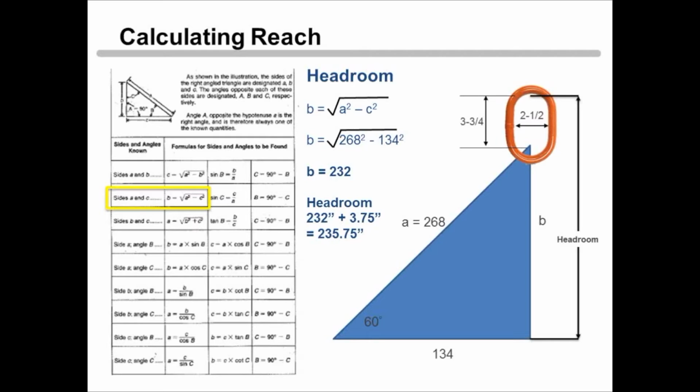So therefore now, is that going to take up too much space? If it's outside, maybe it doesn't matter. So there's two things we need to know. Is the rigging going to work, right? Is that reach going to work? And, okay, great, that achieved my 60-degree angle. And then, of course, how high above the load is that going to work? Because we don't want to find while we're in the air that we're not going to clear something, or it's too high. Then we would have to adjust our slings, which is also going to change our tensions when we do that. And I'm going to lead into that in a moment here.